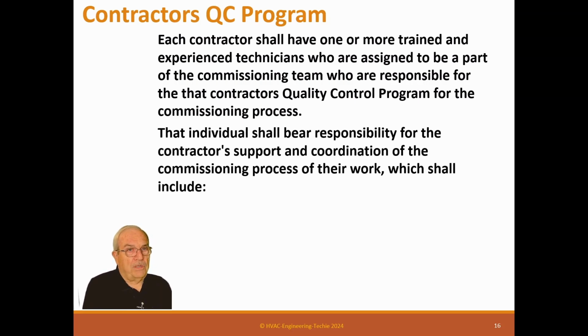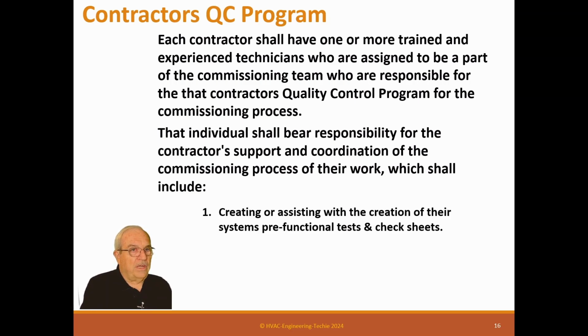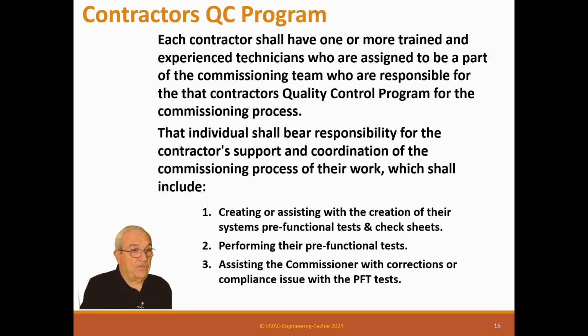That individual should bear responsibility for the contractor's support and coordination of the commissioning process of their work, which shall include creating or assisting with the creation of their system pre-functional test sheets, performing their pre-functional check sheets, assisting the commissioner with corrections or compliance issues with the PFT tests, that's pre-functional tests. So basically, the contractor is actually doing that. You may be observing every once in a while, or you may be checking it and see some problems. He is the guy responsible to get those corrected and get to you.